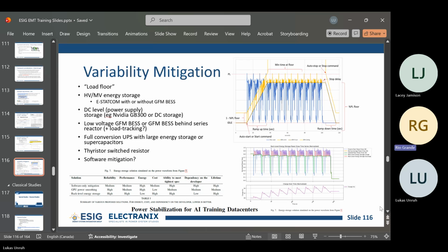So how about thinking if there is a way they can do some calculation of how much of it needs to be shed so that the voltage at their bus goes to 1? So use load tripping to recover the voltage.